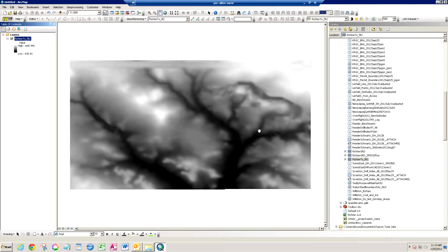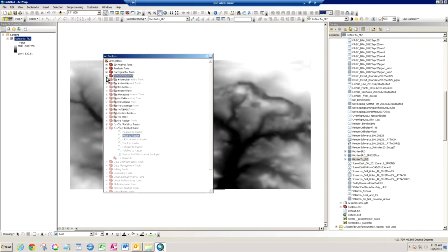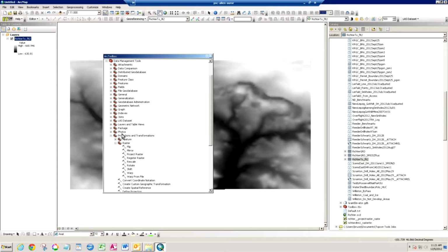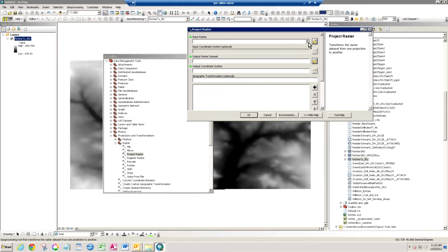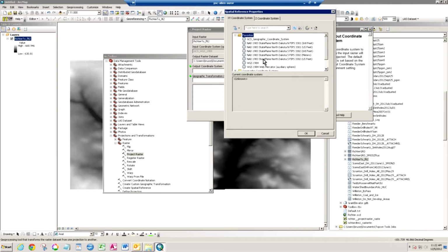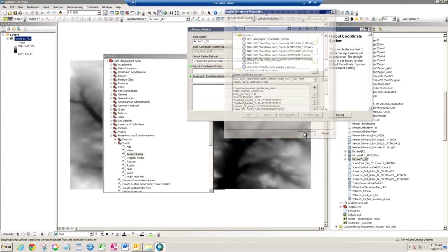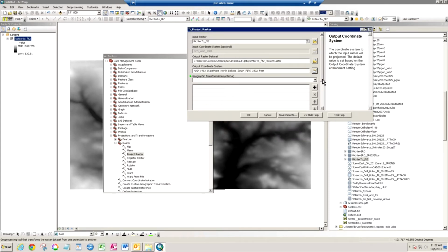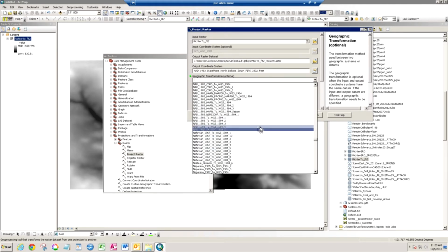To view in ArcScene, the file will need to be reprojected from its native geographic coordinate system to a projected coordinate system. Open Toolbox, Data Management Tools, Projections and Transformations, Raster, Project Raster. A dialog box opens. Select the IFSAR dataset. Select the output raster. If saving to a folder, keep in mind to keep the file name to 13 characters or less. Select a projected coordinate system. When the reprojection completes, the raster will be added to ArcMap.